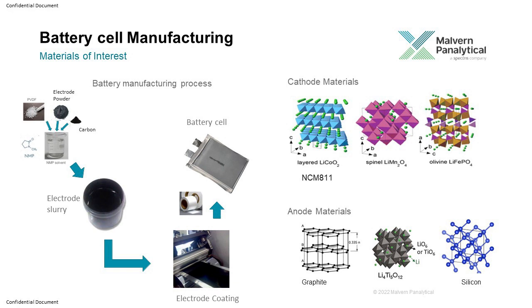Another anode material that is being researched that is more in R&D is the silicon, nanosilicon. Nanosilicon has about 10 times more energy density compared to graphite. But again, the material is not stable. As such, it is stable, but once you charge discharge, once the lithium ions go into it, it expands too much, and then the particles can start cracking.